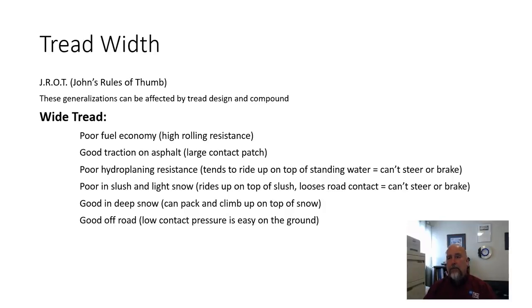So again, with a wide tire, it will roll up on top of and trap more water between the tire and the road. So it's easier to hydroplane with wider tires. Again, with light slush and snow, they tend to ride up on top of that and you lose traction. And in deep snow, they can help prevent you from getting stuck because it'll lift the whole vehicle up off the ground, again, because of that whole contact area kind of deal. And they tend to be good off-road.